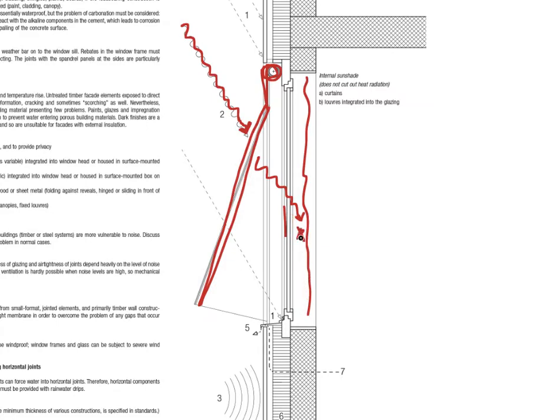Therefore, they are heating up that air. And of course, that kind of gap between the curtain and the glass, that's not isolated from the rest of the room. So if the air inside here is heating up, it will eventually mix with the air of the rest of the room and therefore heat up your entire room, which in summertime can be very uncomfortable.